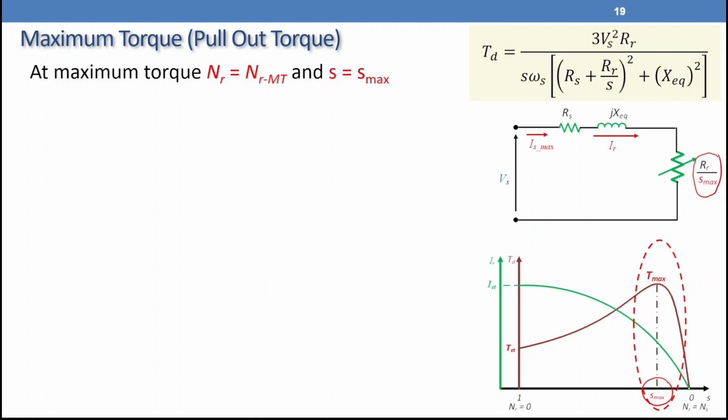We know from circuit analysis, if we have a load like this one, we can represent the source as something like Z Thevenin, and that one is V Thevenin. So this load takes maximum power if we have Z load equals Z Thevenin conjugate. Please return to the circuit analysis theory. So for the Thevenin equivalent, if you would like to transfer maximum power to the load in DC circuit analysis, R load equals R Thevenin. But in AC circuit analysis, Z load equals Z Thevenin conjugate.